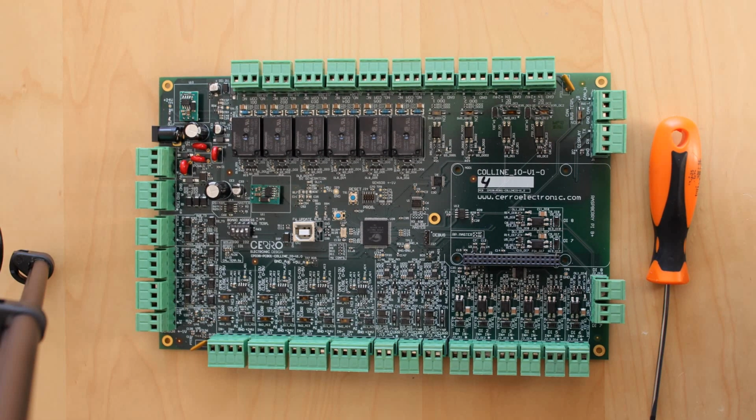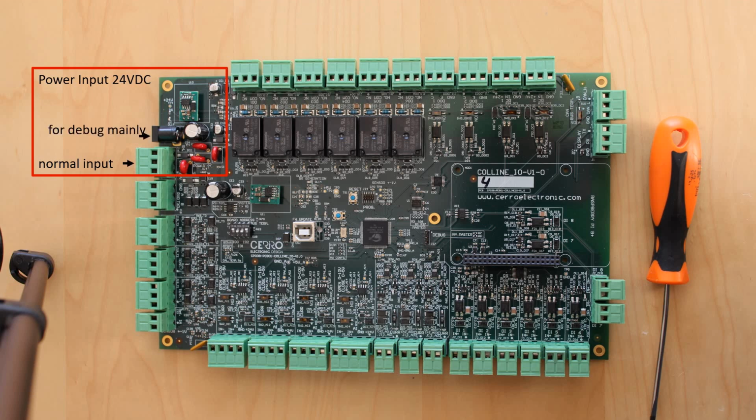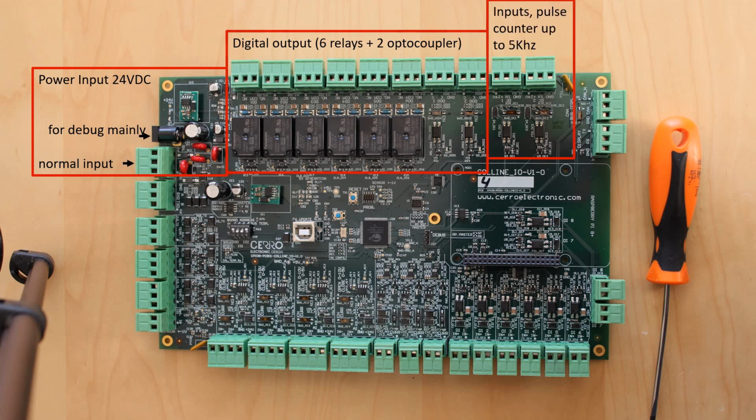This is the board. This is the power area. We have two connectors, the standard or normal connector and another connector mainly for the back purposes. We have here the digital output area, which is based on 6 relays and 2 outputs with optocouplers. Here we have an area of 2 inputs for pulse counter up to 5 kHz, a CAN bus, an RS232 port for displays, for example.